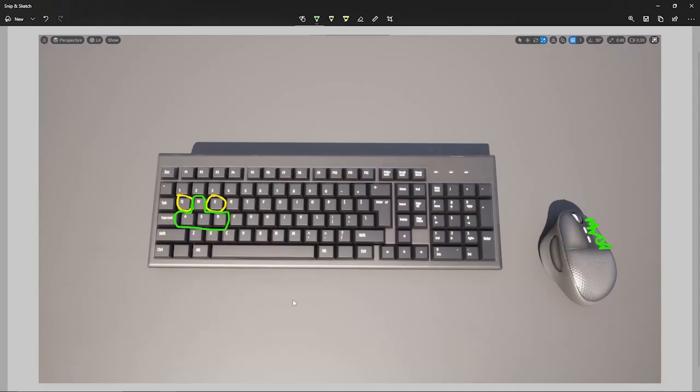Now, as we're moving around, a pro tip is the middle mouse wheel. The camera speed, indicated right up here, is set at 0.33. That is the default speed inside of Unreal Engine 5. The number doesn't really have a lot of context until you start moving around. If it feels much too fast, you can mouse wheel backwards as you're moving and it will slow that speed down. On the opposite side, if you're moving way too slow, for example when we're working with planetary scale, we want our camera speed up way higher. So hold the mouse wheel while you're moving and push it forward, and that will increase your camera speed.